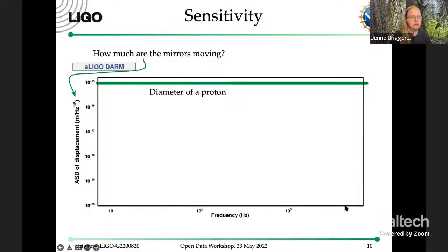So I know that there's been some chat in the chat window during Martine's presentation about what kinds of FFTs and stuff we can use. So that's one thing we do when we're looking at the noise performance of our interferometer. We do an FFT using the Welch's method to look and see what amplitude of data we have at each frequency. So we usually look between about 10 hertz and a few kilohertz.